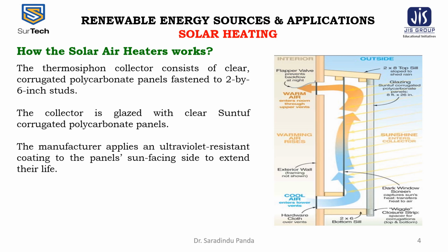A couple of variations could improve the system's performance. Substituting the dual-wall polycarbonate glazing for the single corrugated sheet would reduce the thermal losses through the glazing, although some loss in the energy absorption also will occur.